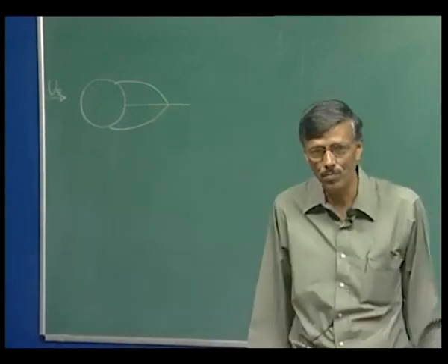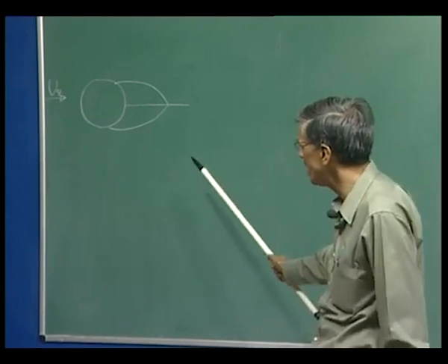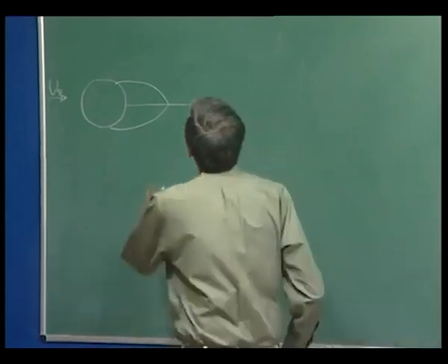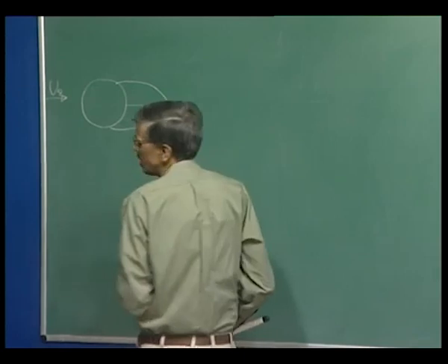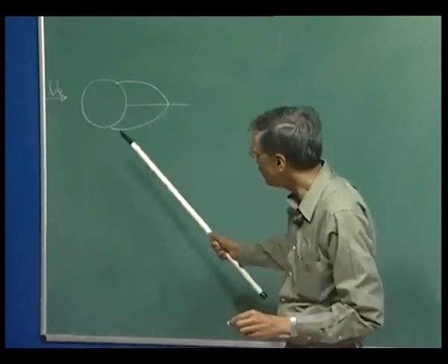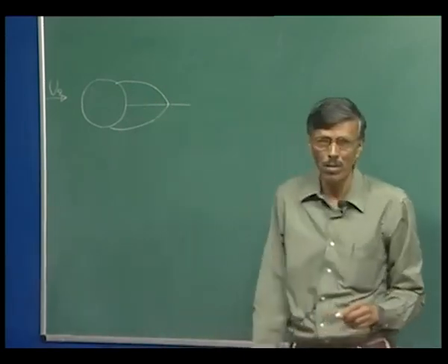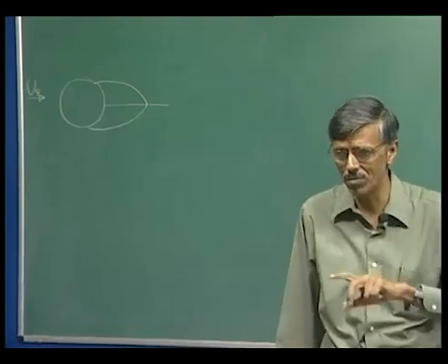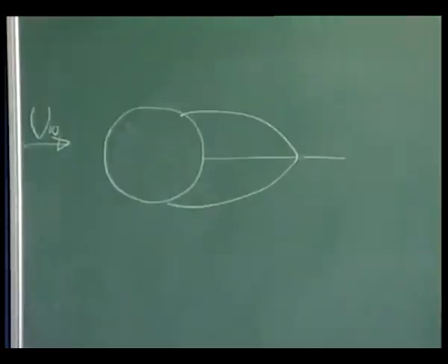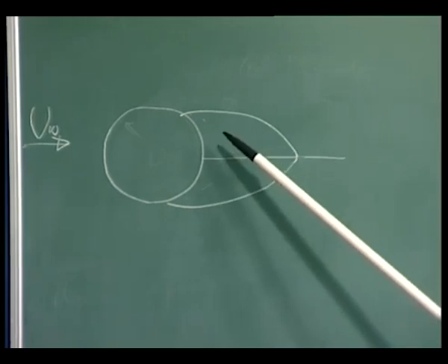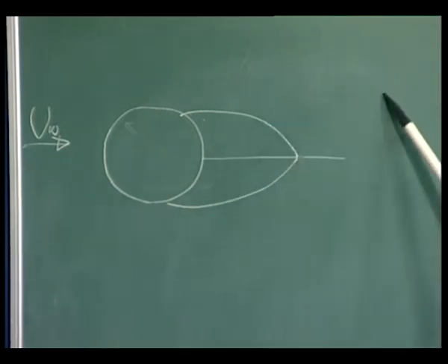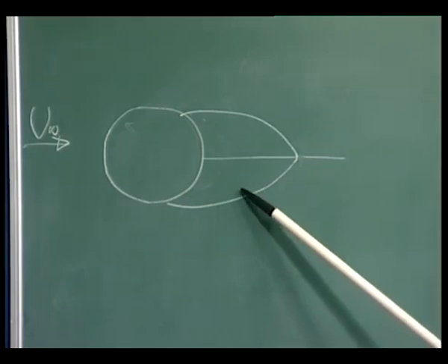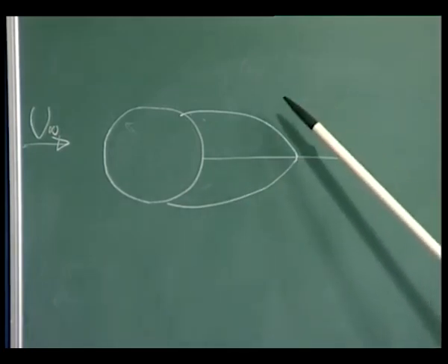But then, if it is a post-critical Reynolds number, one of the bubbles starts growing asymmetrically with respect to the other, and when it grows in sufficient strength, the vortex is shed from that side, while this one gets emaciated as that was growing.